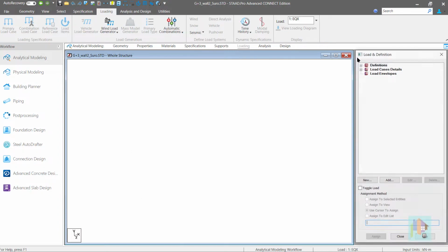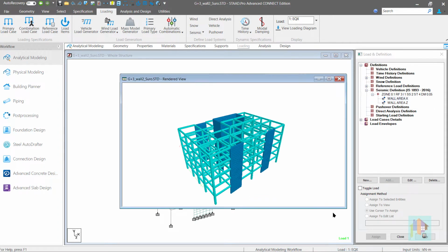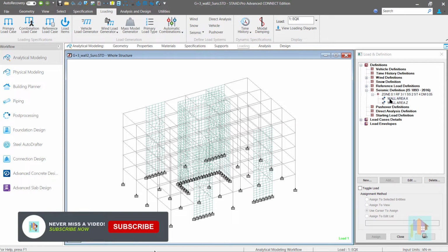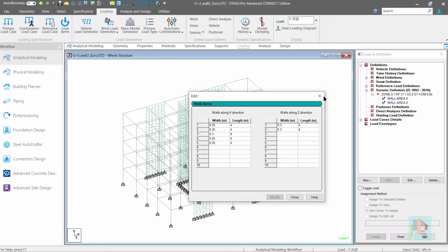I am Surajit Ghosh, and today I will discuss time period calculation for buildings with reinforced concrete and URM infill wall, and how to define this wall information in STAAD in different directions. When a reinforced concrete or masonry wall is considered for analysis, stiffness and load path is modified, which eventually changes the time period of the structure. How we can consider the wall stiffness using a few additional inputs, that I will cover in detail.